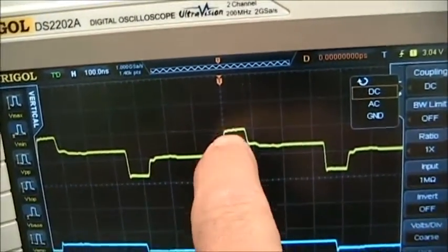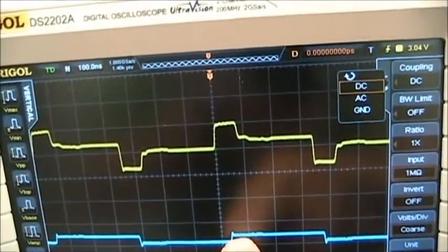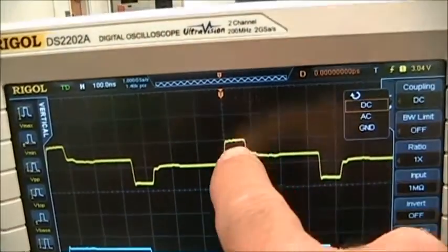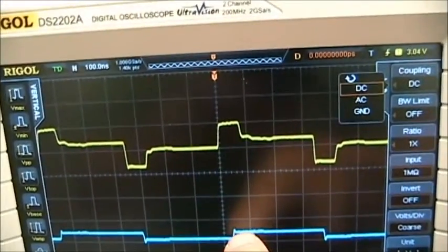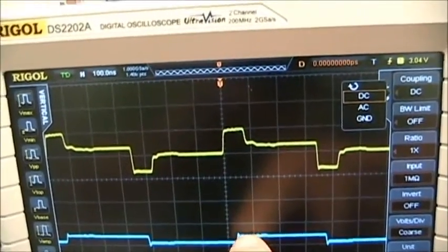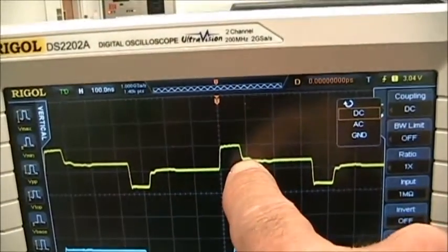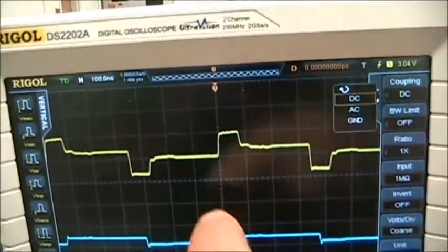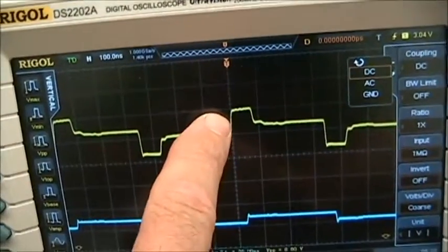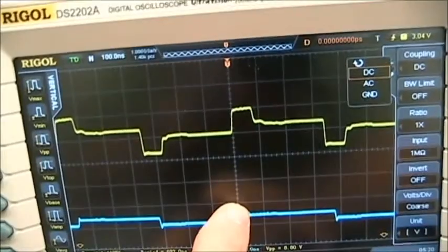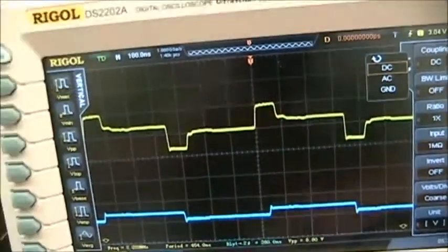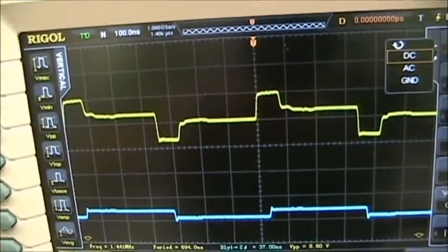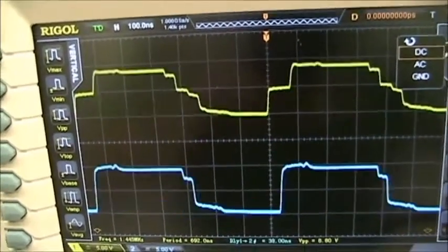The voltage goes down. We see a positive voltage here, but that is smaller than the initial voltage, so the resultant is a negative or a step down voltage. We see that reflected at the input when that pulse travels back to the input. So first pulse goes down, reflected at the load, and comes back. So that's with a minus gamma value of about 0.6.